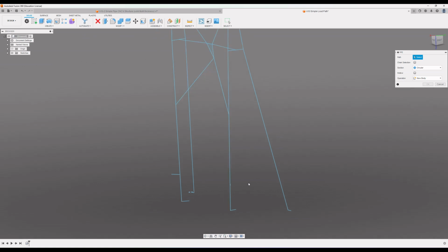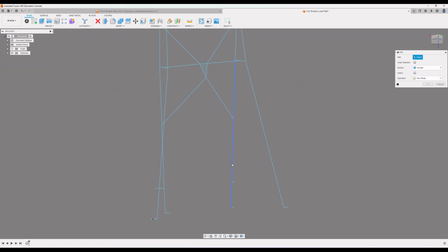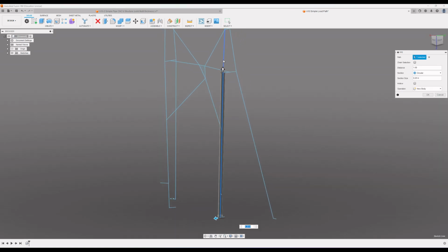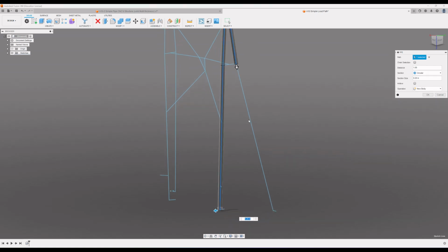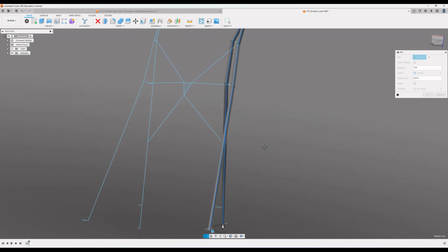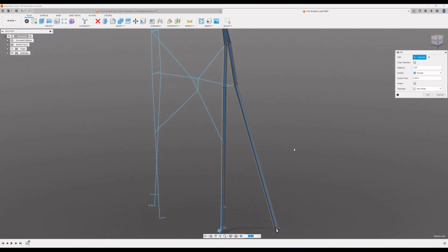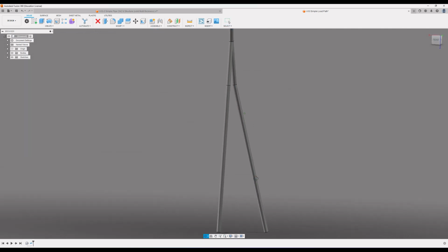We turned off tangencies because a couple of these lines are lines of force that lead to the center of our bolt, so we don't necessarily want to add anything there. The other important thing to note when you're using this tool is you do want to try to create the pipes in a way that they would normally flow. So here we know that these pipes would flow up and around the side. This gives them more realistic connections as you're going.